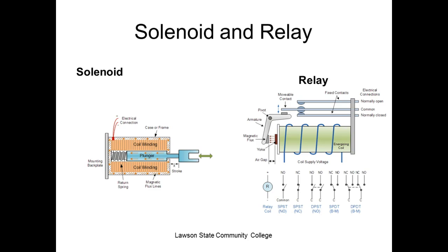A solenoid, we use that same feature. I didn't put my camera up, guys, so y'all can see this. This is nothing but a straw. But instead of using a regular wire, I'm using what they call magnetic wire. Magnetic wire is wire that has really, really thin insulation. And why we do that is you want to get really good coupling between the wires so those fields combine. And all it is is just a straw.